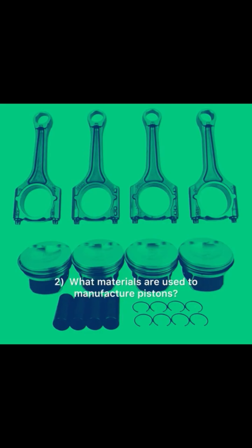2. What materials are used to manufacture pistons? Aluminum. Hypereutectic aluminum. Cast iron. 3. How is piston slap controlled in an engine? Piston pin offset. 4. What are piston balance pads? Area of extra metal that can be removed to balance. Near the pin boss. 5. How does the piston expand with heat? Diameter across pin boss expands more, more material. Piston head expands more closer to combustion.